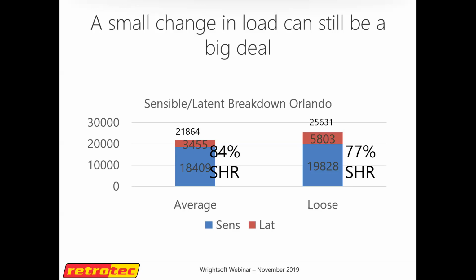So when that system turns on and it runs, what's going to happen if the system can do a lot more temperature control than moisture removal, and you have a house that needs more moisture removal than normal, is the system's going to run for an hour. It's going to cool things down. It's going to do its job. It's going to satisfy the temperature, but it's going to satisfy that temperature before it's had a chance to remove all that moisture. And so we call this a short cycle, right?